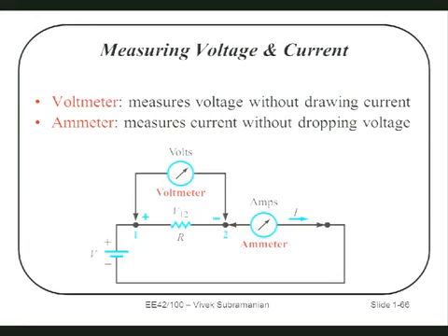So that the resistance of the voltmeter doesn't mess with the resistance that I measure over here. So voltmeters should ideally have infinite impedance. They typically don't. Typical multimeters will have input impedances on the order of 10 megohms. Okay, that's pretty typical. So it's a large number, but it's not an infinite number.